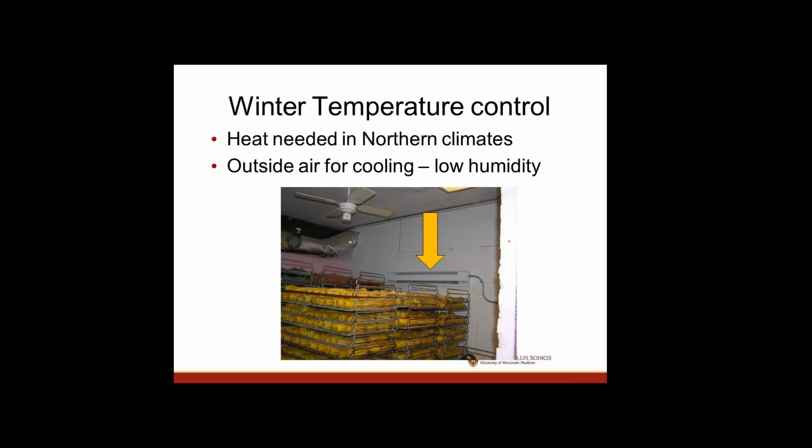The other thing, you know, freezing can be a problem. My collaborator on this project lost a cooler full of carrots because it got too cold during one winter. And people laugh when I say, in northern climates, you need a heater in this cold storage, because if you get temperatures lower than the storage temperatures, you're going to have heat loss out of the storage facility and require some heating to maintain that.